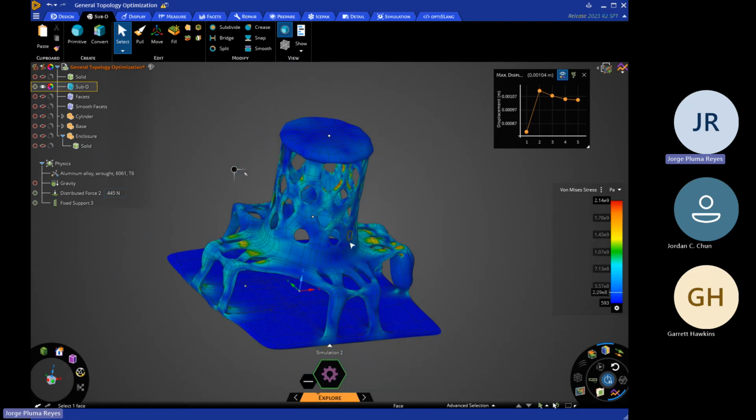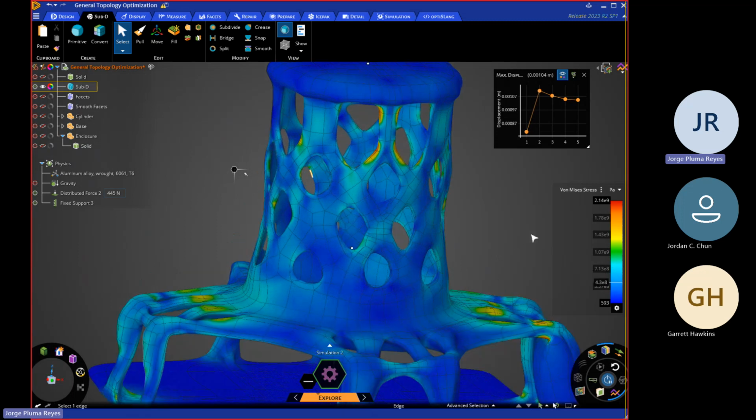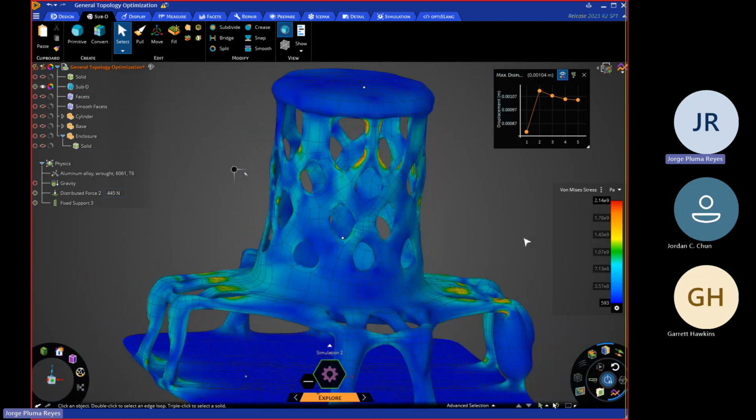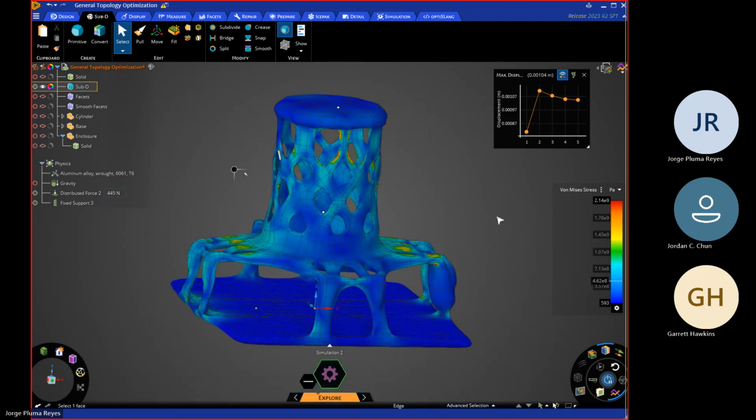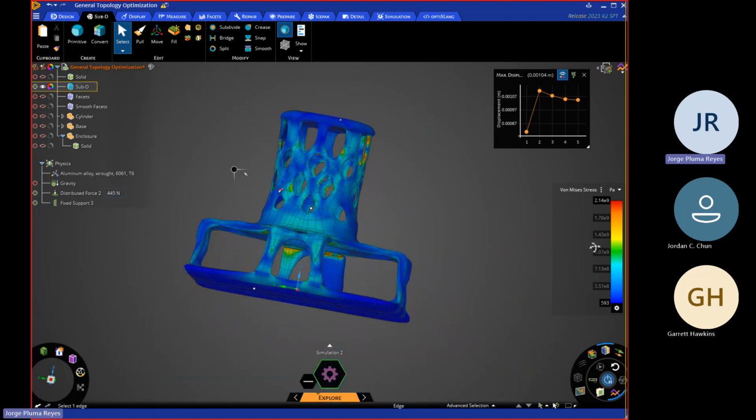Since this is more of an organic body, you can't really look at it from a face or a circle and a parameter. It's a little more tricky. So I'll definitely follow up on that in case there's a trick I don't know of, but I think the answer is just being careful with your changes and tracking them, using Control Z to your advantage.